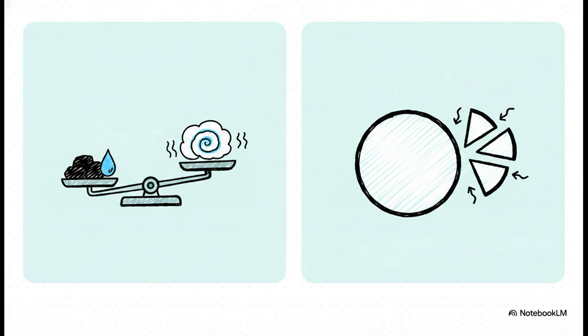wasted heat. Engineers actually evaluate this in two different ways. The direct method is pretty straightforward. You just compare the steam energy output directly against the fuel energy input. Easy, right? But to find out exactly where you're losing efficiency, you really need the indirect method. Instead of just looking at the steam, this method starts with an ideal 100% efficiency and systematically subtracts all the various individual heat losses mathematically to find out what you actually have left.